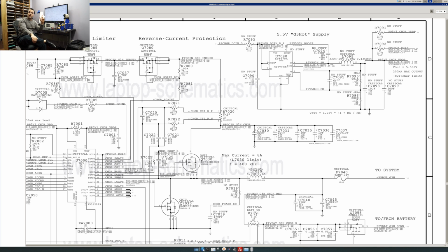Now, here's what happens when it doesn't want to work off the charger a lot of the times. One of those 10 ohm resistors will be blown, will be destroyed. So one of the resistors will be 10 ohm, and one of those resistors will be something silly like 500 ohms or 1,000,000 ohms or infinite resistance and blown. And what happens when that happens is that it will sense a huge difference in voltage between the top and the bottom.